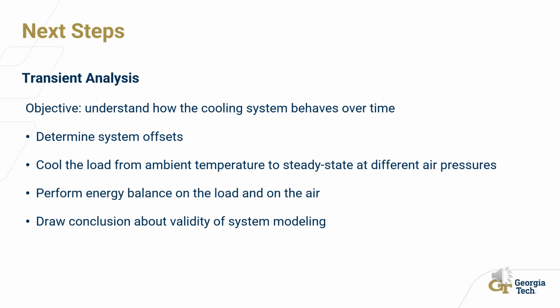This leads us to our next step, in which the team will perform a transient study of the system to understand its behavior with respect to time. This will involve recollecting offset values, assessing the system's response to an input pressure of 40 psi from the compressor and to an input pressure of 80 psi from the building's air supply.